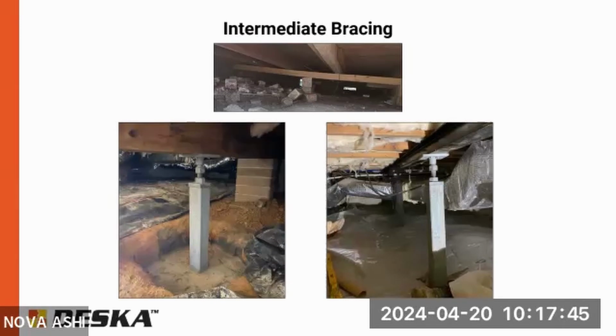So it depends. If it's on the exterior, it has to go down to the frost depth, which in this area right here, it's 24 inches. If you go up to Minnesota, it might be 6 feet. In the middle of the winter, the ground can freeze, and just like a can in the freezer, it will expand, and it can cause the structure to heave if the footing isn't deep enough. If you're in a crawl space, it's sheltered. You typically have perimeter walls, and ideally conditioned space above it. It stays much warmer, so typically about a foot.